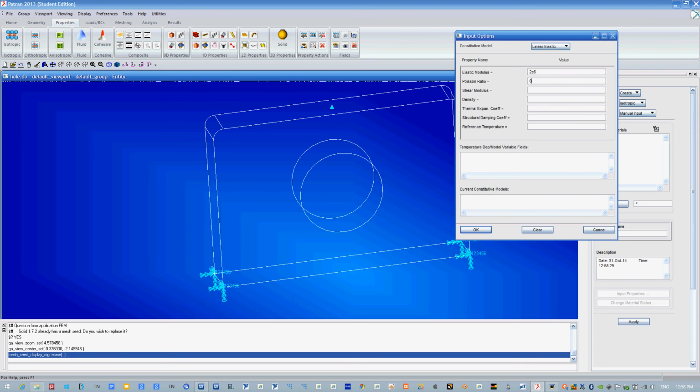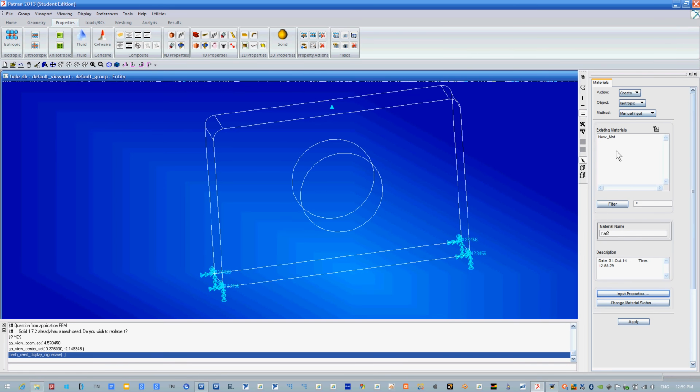The one thing to be extremely careful with is that Nastran Patran is unit independent. You need to watch all the units. You can plug whatever you want into this and it will give you numbers in the end, but it's up to you to be sure about the output. I know it was a huge issue last semester, and Nastran and Patran actually publish a little table online saying if you use these input values, these are going to be your output values for force, displacement, and so on. So you can do it in either the SI or the imperial system. It really does not matter.